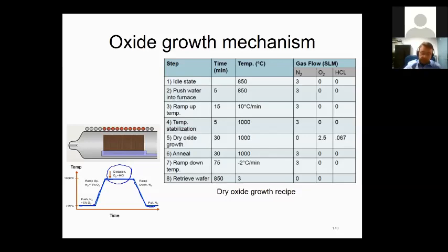If you do not wait for the cool down or the ramp up, first you can harm the tool because it can't catch up with the speed. Secondly, and maybe more importantly, you can build up a lot of thermal stress on your wafer. So all these wafers, once they are taken out from, let's say, 1,000 degrees to outside room temperature, 25 degrees, there's going to be too much of a sudden abrupt change in temperature, and it may build up an unequal amount of stress on certain points, and it may just break the whole wafer.